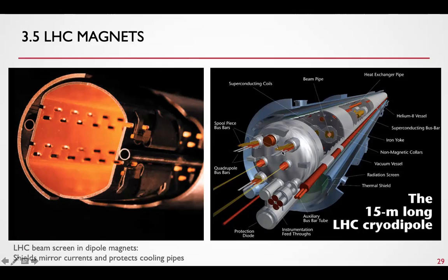It's a system that works. However, if there's some problem at the junction, the ohmic resistance explodes from nano-ohm to milliohm. That means you get enormous heat deposits, and the superfluid helium evaporates very quickly. That's how the cooling functions.